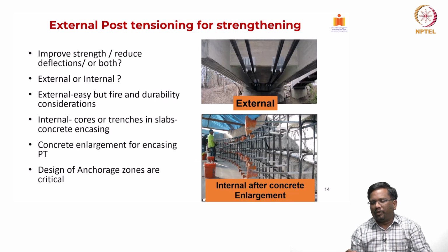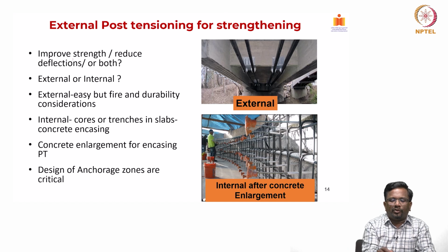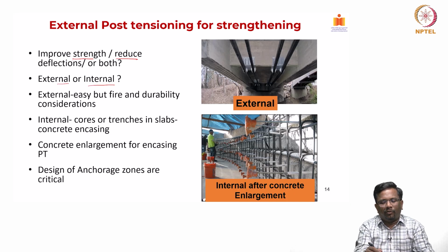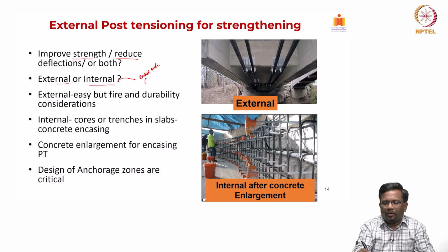Now, where are we going to use this external PT for strengthening? We can use it to improve the strength, reduce the deflections, or most of the time it will be required for both. And it can be designed as an external system or an internal system. How do you do that as an internal system? I put external PT, but then I can encase it with concrete jacketing,